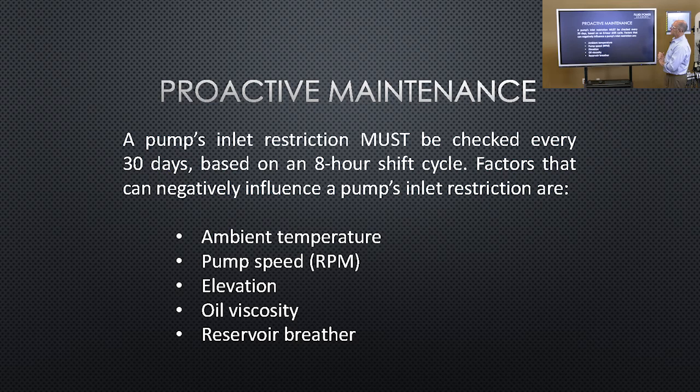Proactive maintenance: a pump's inlet restriction must be checked every 30 days based on an 8-hour shift. Factors that can negatively influence a pump's inlet restriction are ambient temperature, pump speed, elevation, oil viscosity, and of course, reservoir breathers, screens in the reservoir, etc.